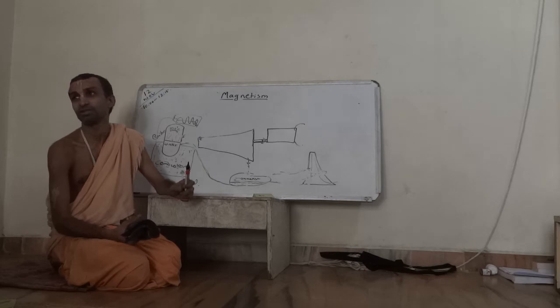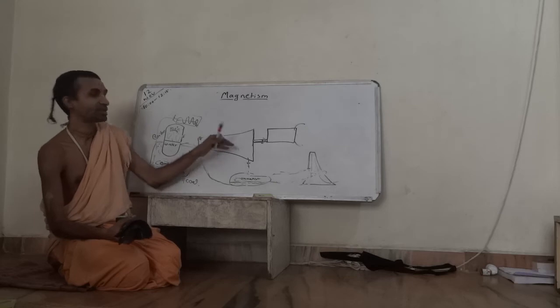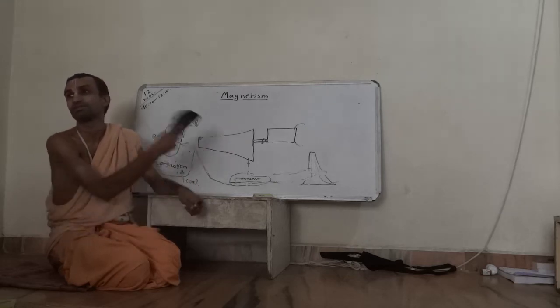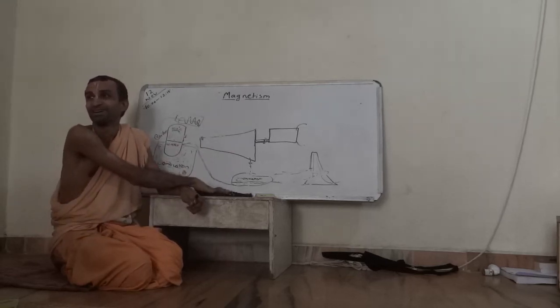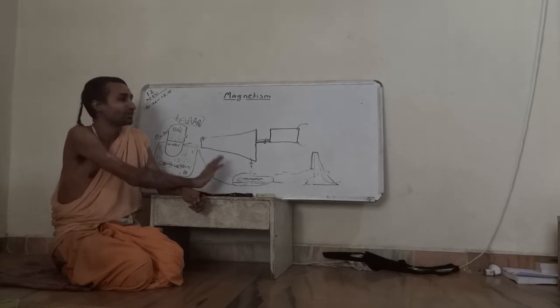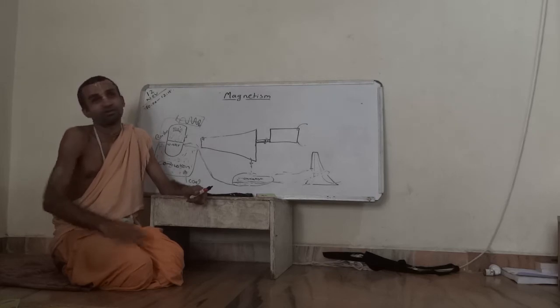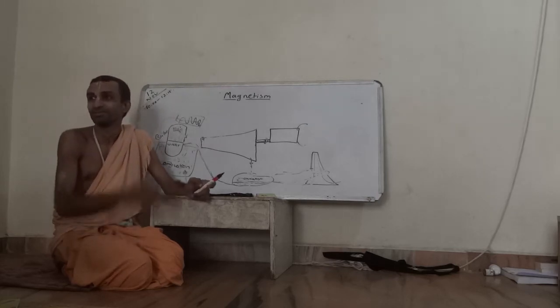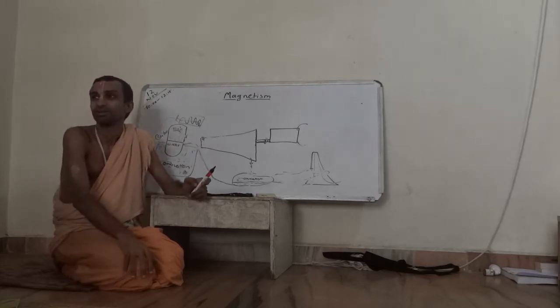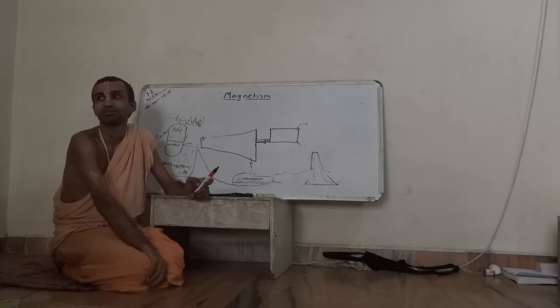If you go beyond 600 degrees centigrade, then the machines will start deforming because the material of the machine is not so strong. So the material of the machines defines how much superheated you can go. Otherwise we can go 1000 degrees also, but machines are not able to take it.